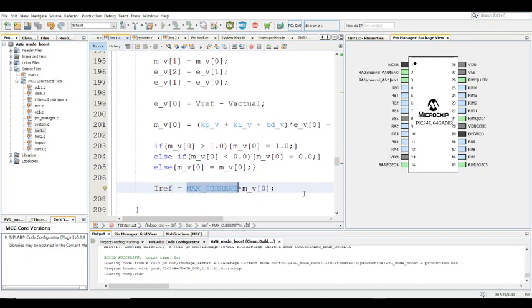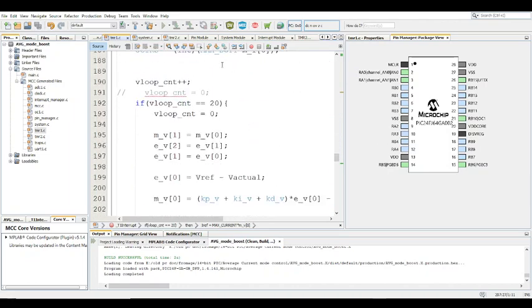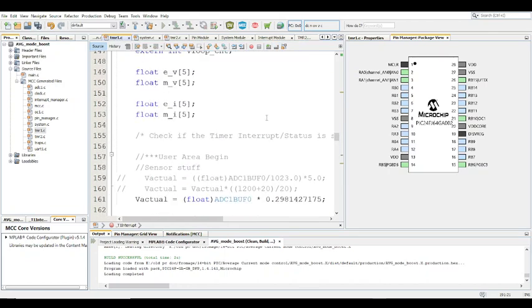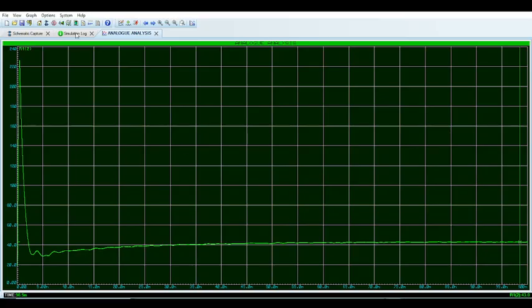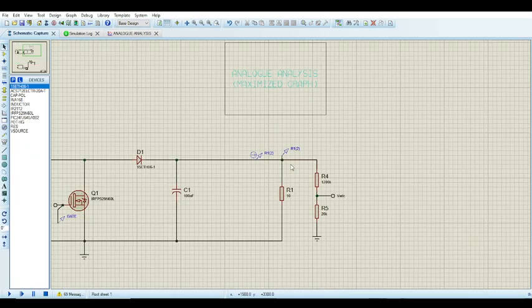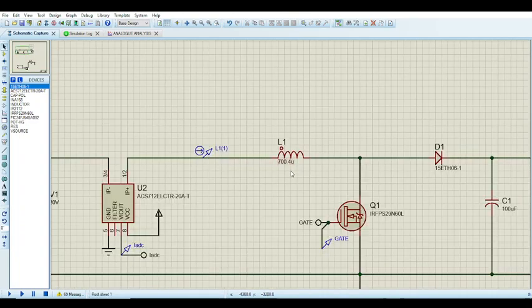And if you're having instability issues, disable the outer loop, work from the inner loop, and sense that, and give yourself something on your hardware such that you can monitor the current going through the inductor independently. You can actually see what it is. Don't make everything so inline. You prototype anyway. Try to see that, okay, I can at least see what current is going through the inductor.